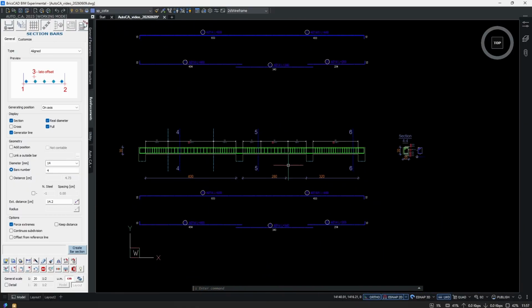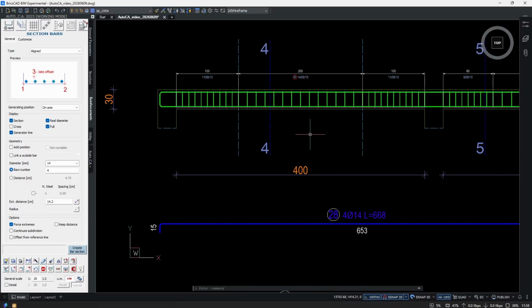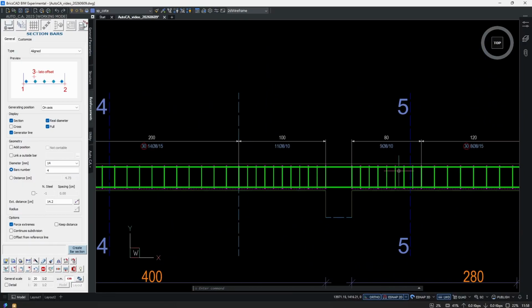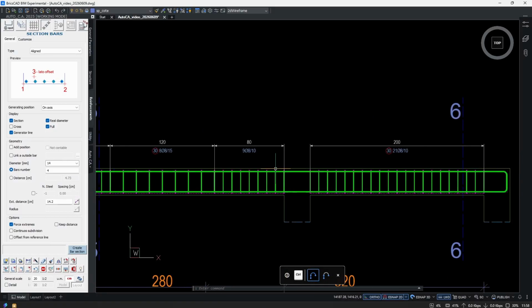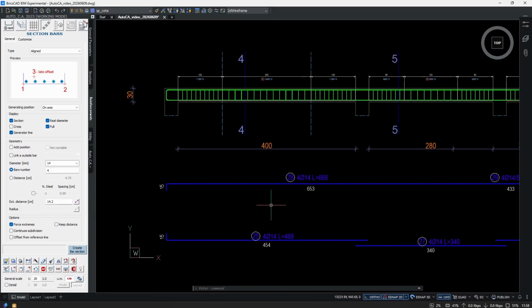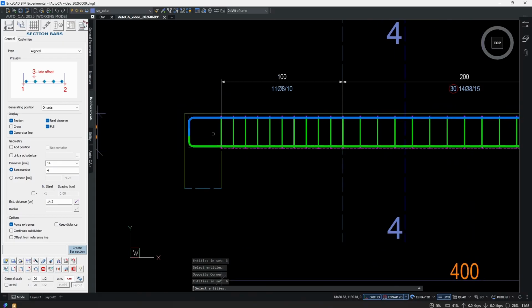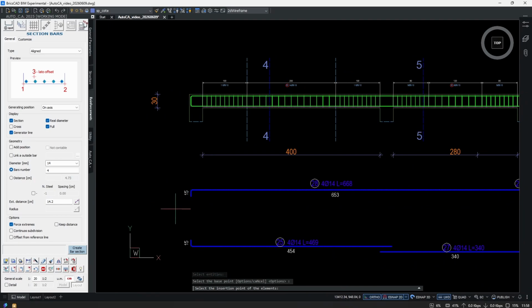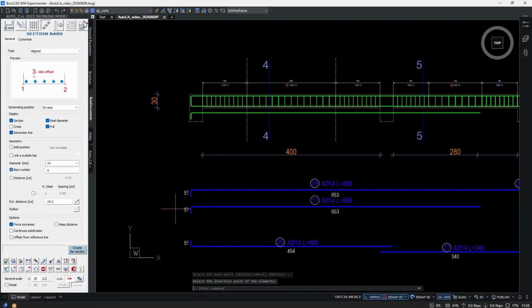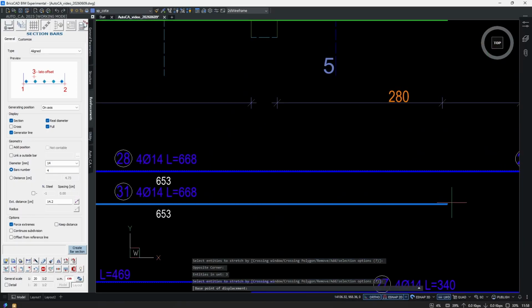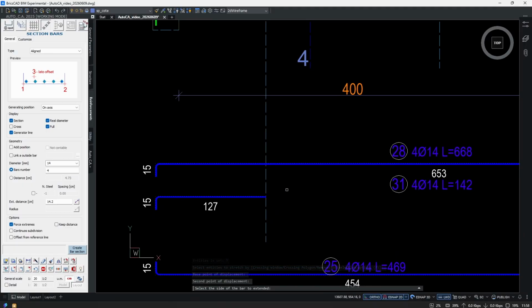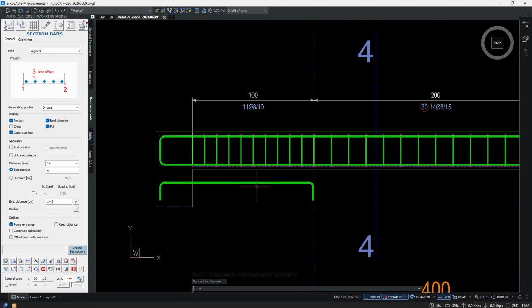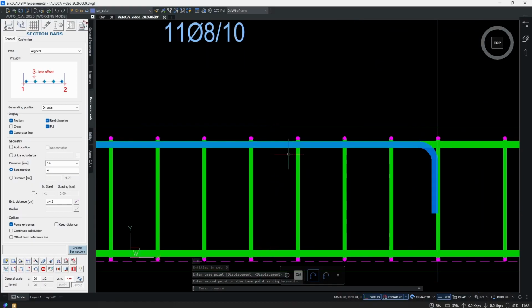Another thing is if you want to add some 3 bars into these outside zones of the distributions, you can do this by copying both the inside and outside bars on the upper section. I'm gonna copy these 2 a little bit lower. I want this one to reach only to this point here. So I'm gonna stretch it and give it another hook on the other end. Okay, the inside bar follows the same shape. I'm gonna put it up here.